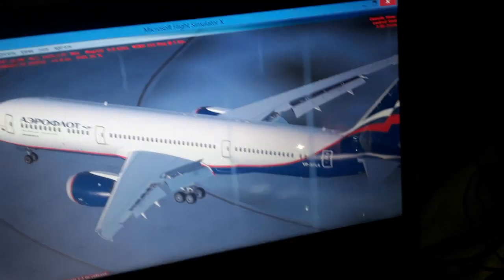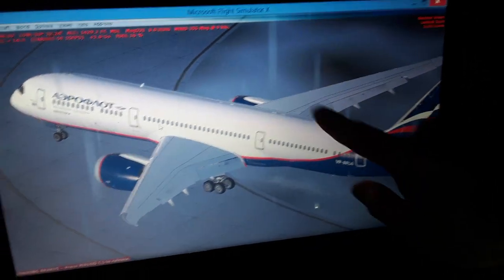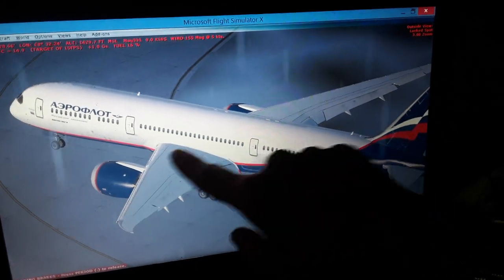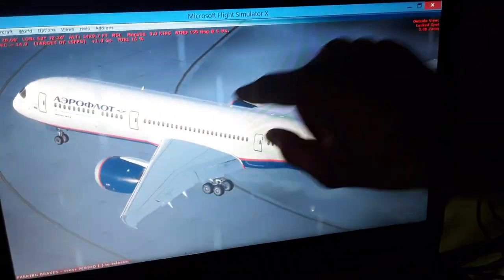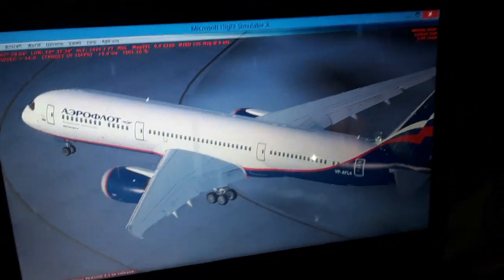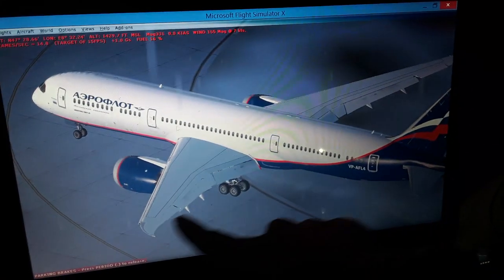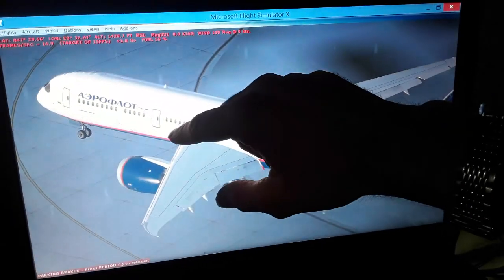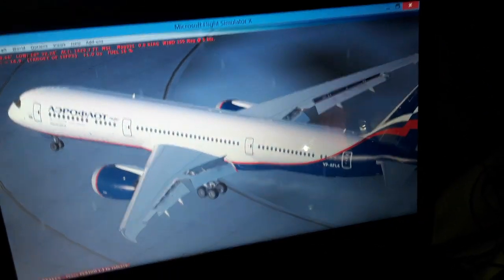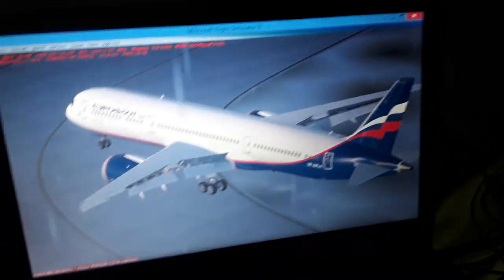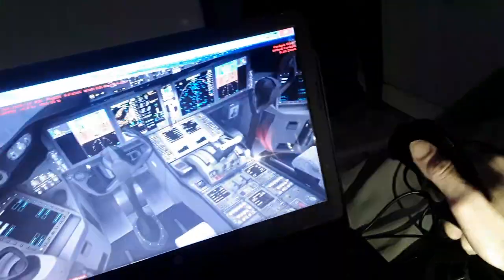Also, you can see the top surface of the wings is more curved. So as we fly, using the Bernoulli theory of fluids again, the airflow is moving much faster above the wings, so there is a lower pressure which sucks the aircraft weight and wings up into the air. Also you can see there is a differential pressure, higher pressure below the wings and lower pressure above the wings. You see also the spoilers extended now. The speed brakes of the aircraft can act also as roll spoilers in flight.